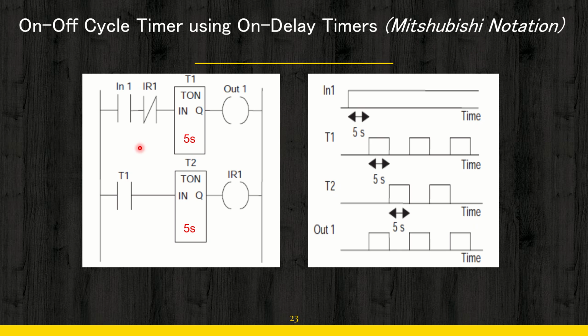I will again brief it. Initially you see that this is not activated, your output is not activated, it is low. And since your output is low, definitely you are having a low signal at the output, no problem. Now you apply the signal in. You do not put it off, you apply the signal here. That means this open switch becomes closed. Once this open switch is closed, your timer will get the trigger. Once the timer is triggered, after 5 seconds, it will be on.